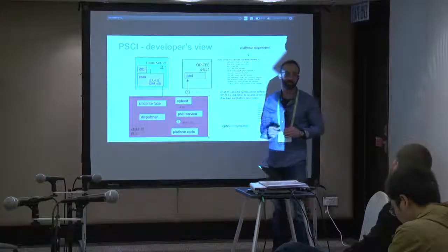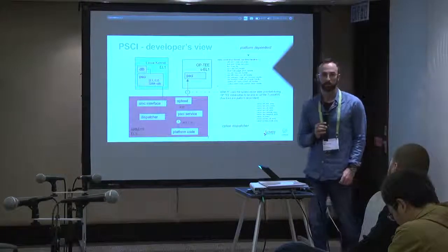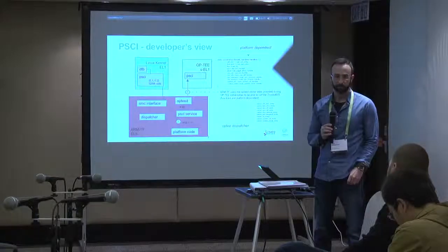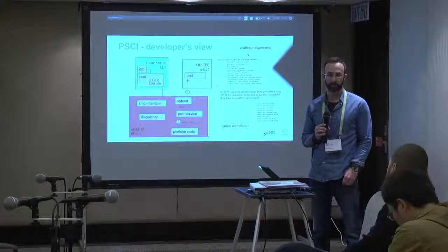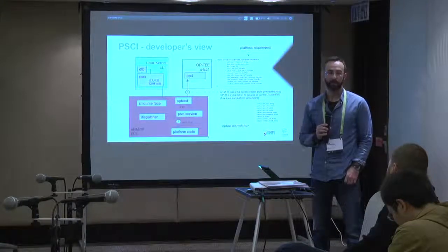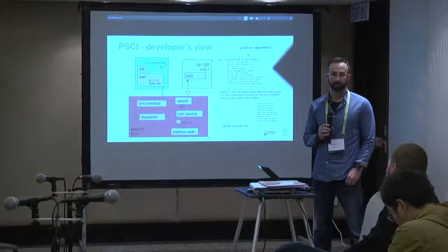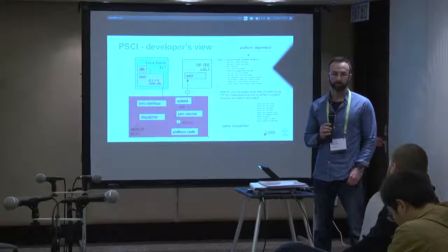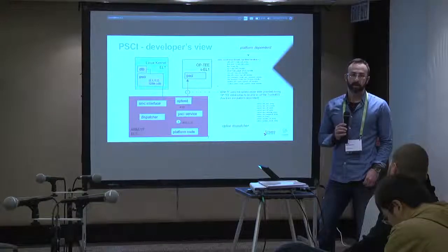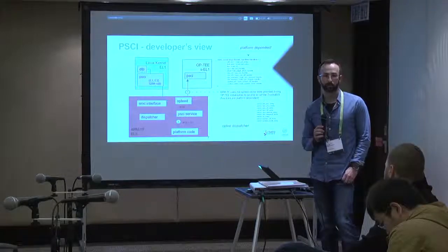So this has been a problem on ARM32 firmware for a while, where we have hacky CPU idle implementations, where a lot of times the firmware is stuck on CPU 0, so you can't idle the cluster until CPU 0 is done. The hardware doesn't have the restriction, but the firmware actually has the restriction. The firmware, yes. But I just wanted to make sure.